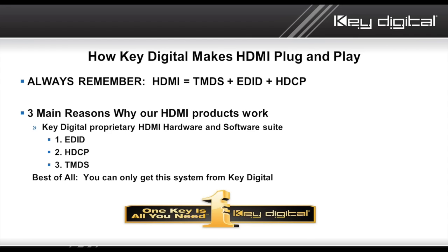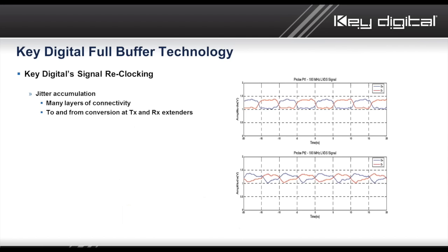Now, here's the thing. We're talking about extenders. We're going to give you tools that will allow you to extend video and audio, HDMI, 1080p for example, up to 600 feet, or 4K over 100 meters. It's not all short-length HDMI connections, is it? Wouldn't life be great if it was just source to display with a 6-foot HDMI cable? That's not the world that you live in, nor is it the world that KeyDigital lives in. And so every one of our products that you see today, and if I'm not mistaken, our entire product line of hardware as well, all feature reclocking.